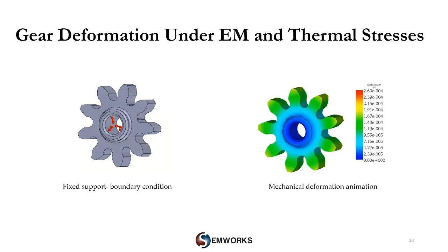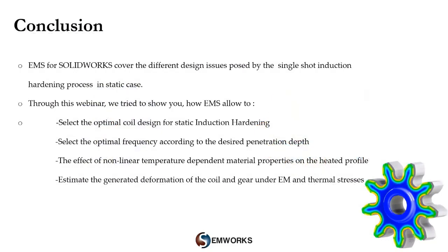Now we conclude with those results. To summarize, EMS for SolidWorks covers the different design issues posed by the single-shot induction hardening process in static case. Through this webinar, we tried to show you how EMS allowed to select the optimal coil design for static induction hardening and to select the optimal frequency according to the desired penetration depth.